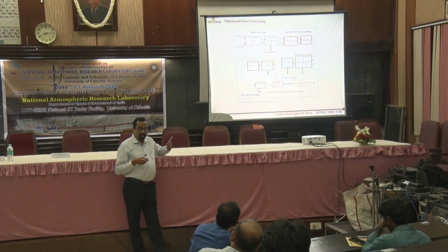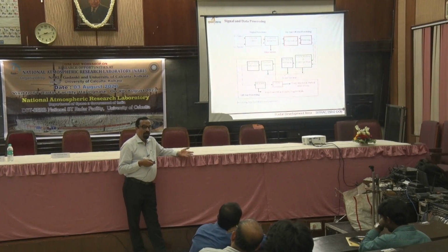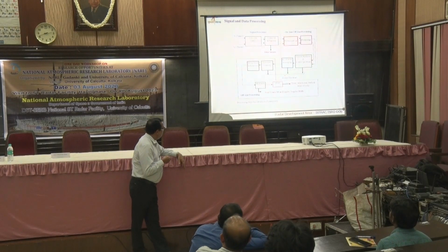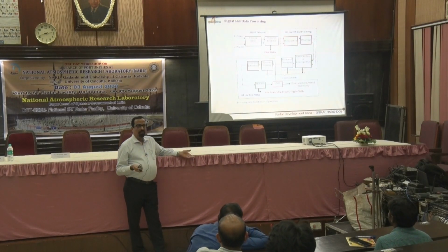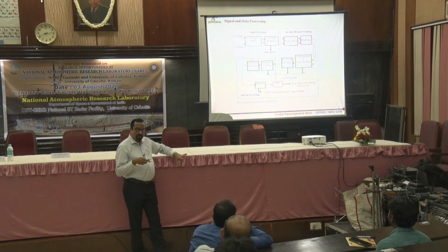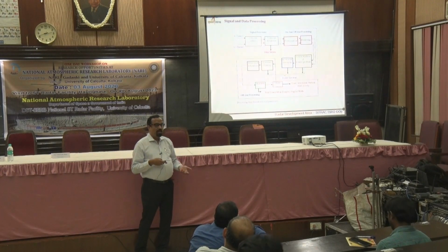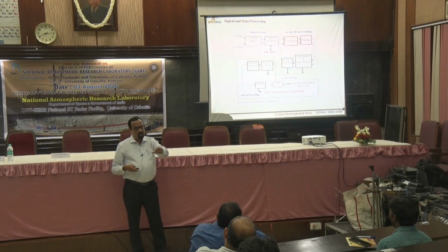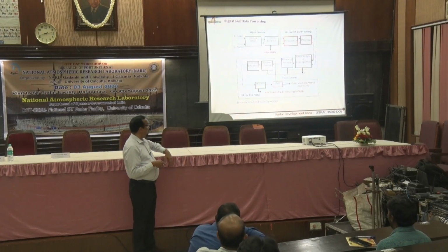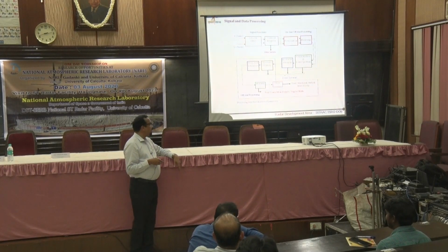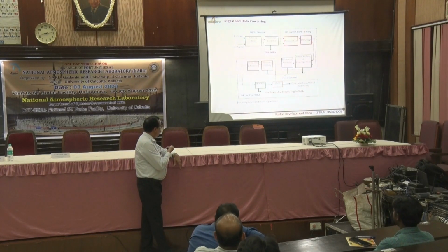Both have different gain. Again, the signal processing parameter comes in: what you should do and when you are supposed to do it. Then we do spectrum cleaning. Whatever you get need not be good; it has to be cleaned properly. Then we go for noise level estimation, because whatever you receive through the receiver contains all types of noise. It will create base noise floor fluctuations, and you will have a small signal component. So you have to do noise level estimation, bring the noise down, and extract the signal out of it.